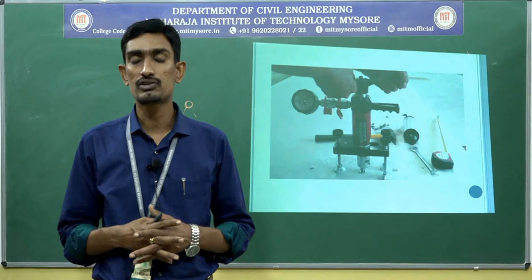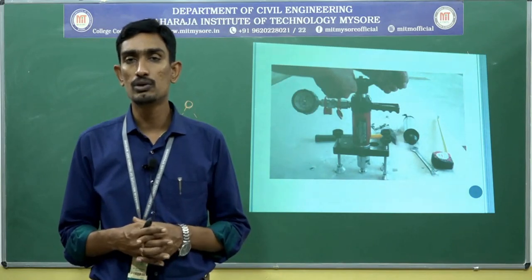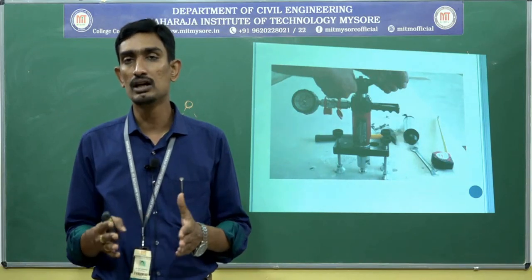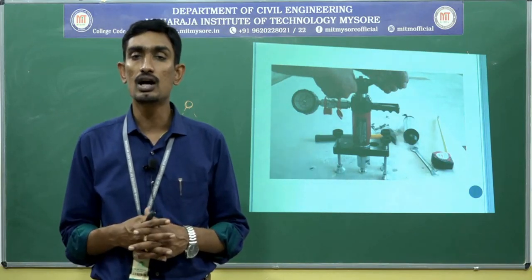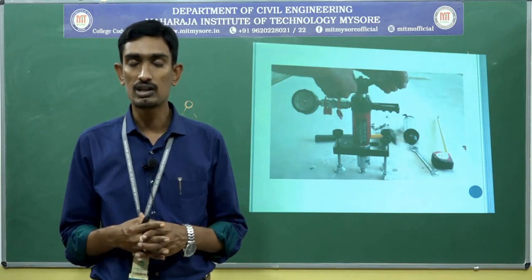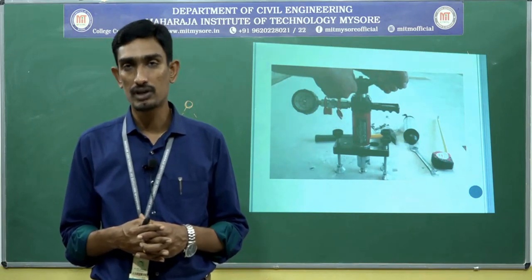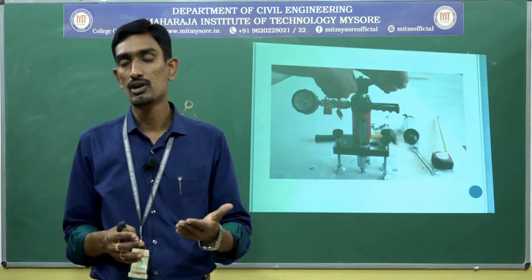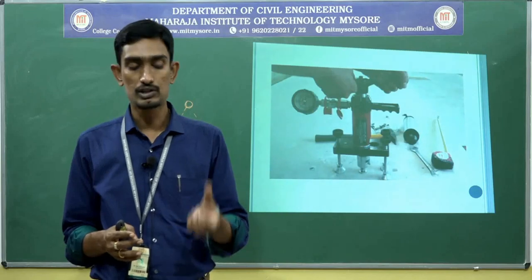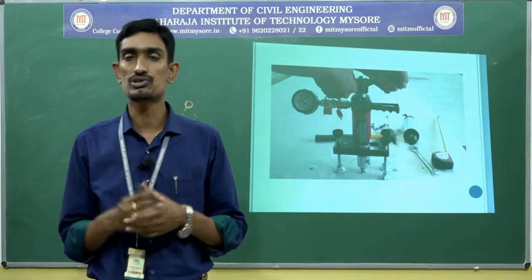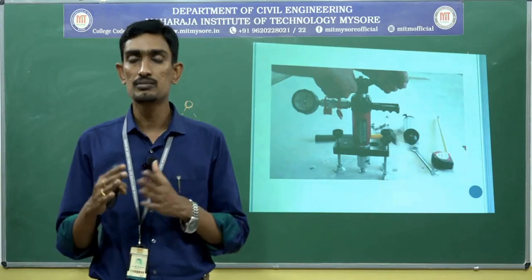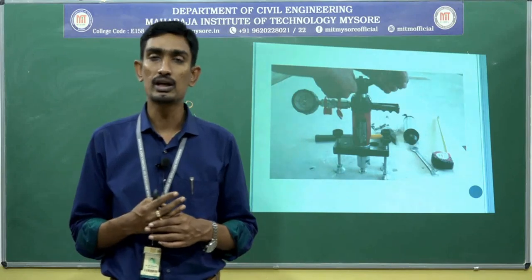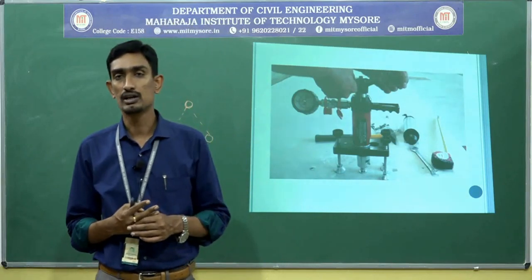So these are the two tests I am going to use in order to perform the semi-destructive method of testing. Today we have learned the penetration resistance test or Windsor probe test, and the second one I have explained is the pull-out and pull-off test. Is it clear? In the penetration resistance test, I correlate the exposed length with compressive strength. Here, force in terms of compressive strength. So these are the things we do in these testing techniques.